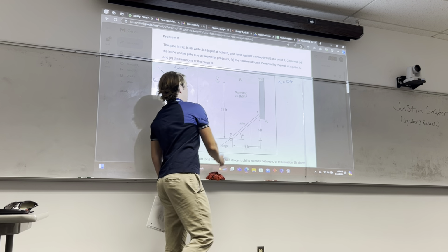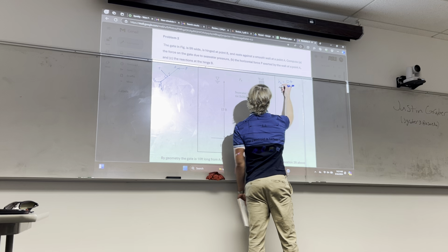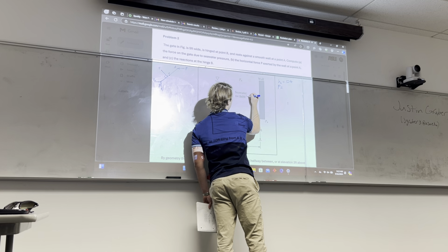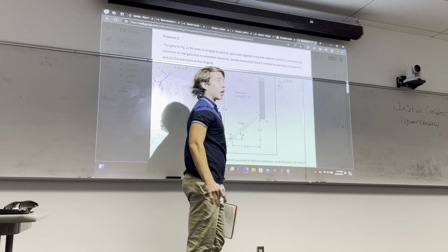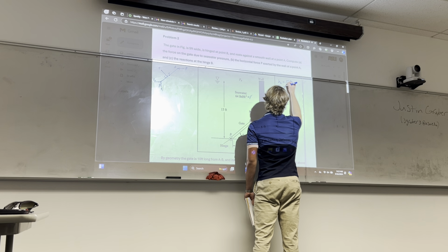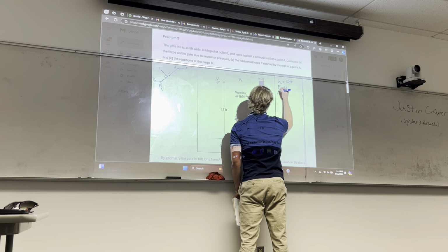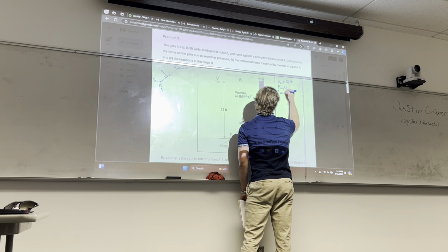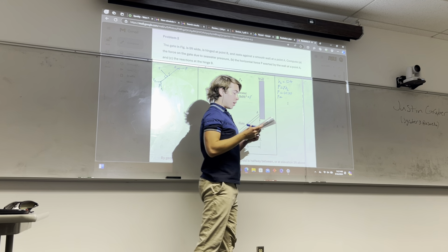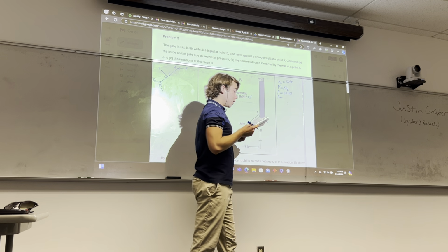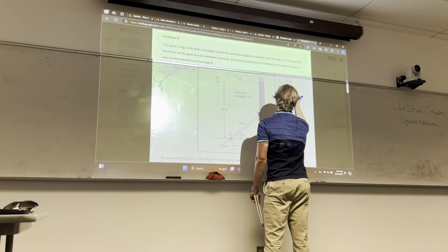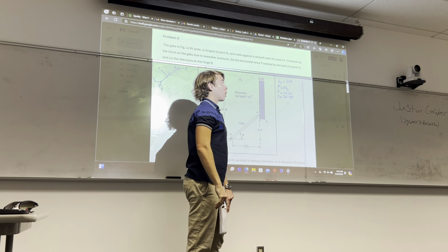So now to find the pressure, we go pressure equals, in this case, this is our gamma, that's our rho g term. So pressure equals gamma times HC. In this case, we have P equals 64 times 12. Our pressure equals, someone do that math for me. Oh, never mind, I got it. 768. And that's PSF, pounds per square foot.